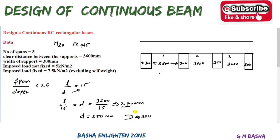Here the effective cover will be approximately 50. If I choose 250 and 300, fine; if you choose 240 by default and choose overall D around 300, then the effective cover will be around 60 mm. So it is your wish, and you can check whether the depth you have taken meets the required criteria or not. I will show that point also.